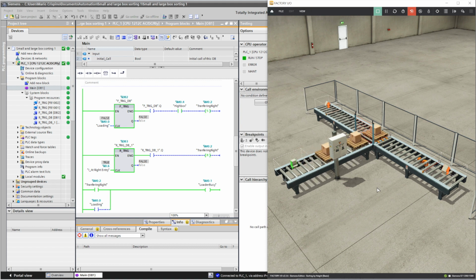So let's see how many pallets can be on the right conveyor at any one time. Okay, the first one is transferring right while the next one is waiting. Then the next one starts loading and starts transferring right while the previous pallet passes the right exit sensor and is then removed. So it's clear to see that even when the maximum amount of pallets are being produced, the maximum number of pallets that can be on the right conveyor at any one time is 2.